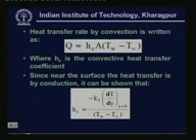Now, the basic heat transfer rate by convection is written in a very convenient fashion as Q is equal to HcA into (Tw minus T infinity), where Hc is the convective heat transfer coefficient, A is the area of heat transfer, Tw is the surface temperature, and T infinity is the temperature of the fluid in the free stream. This equation, which is called the basic equation for heat transfer by convection, is also known as Newton's law of cooling. Basically this is a definition of the heat transfer coefficient. It is not actually a law, but it defines the heat transfer coefficient.